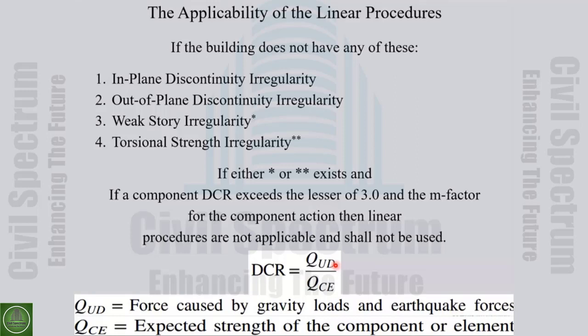We can accept some level of plastic deformation, some level of damage in them. And there are some other response parameters, depending on the system and material, that are brittle. So we call them force control parameters.